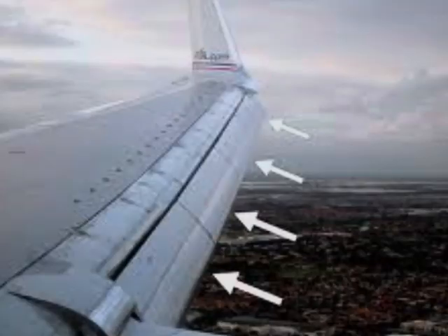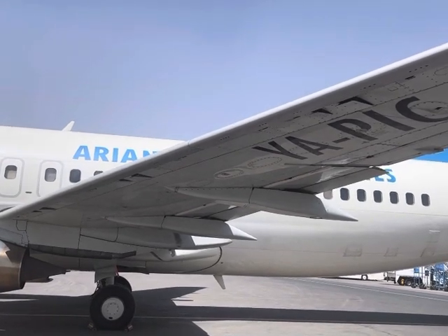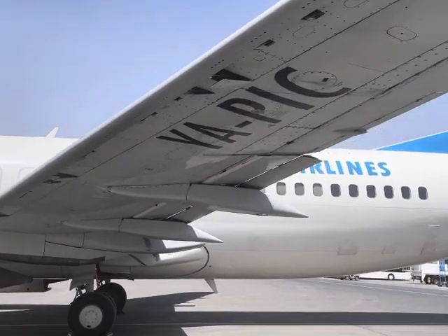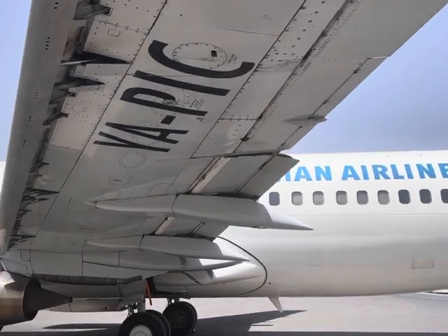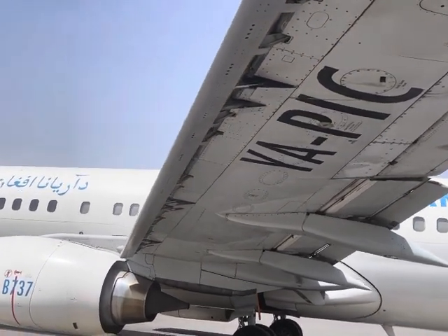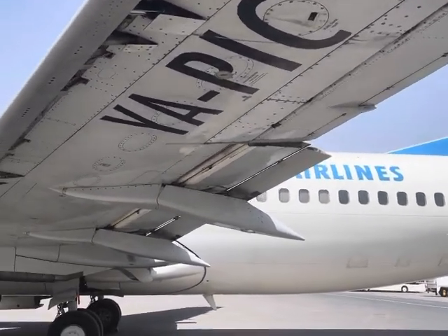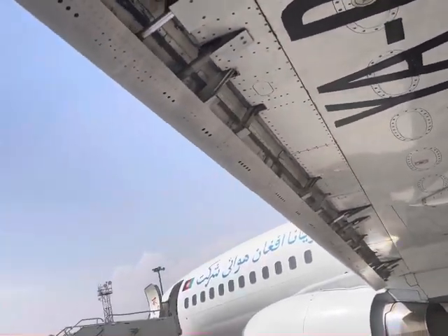During approach for landing, it is the same. We have lesser speed, so lesser speed means lesser lift generated by the wing. But increasing the surface and the curvature of the wing will enable it to generate more lift, and more lift will enable the pilot to reduce the speed, because we are coming to land on the runway with lesser speed. The landing speed is lesser than the descent speed, lesser than, for example, the cruise speed.